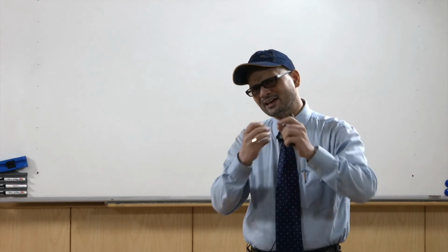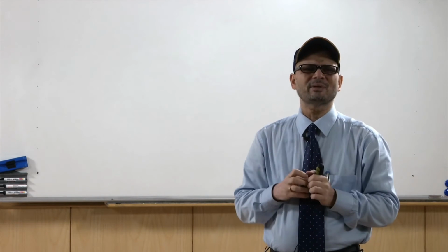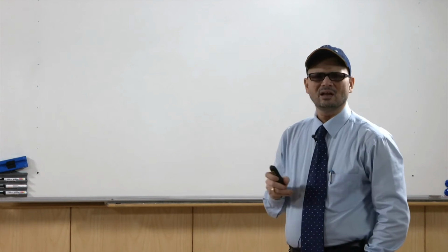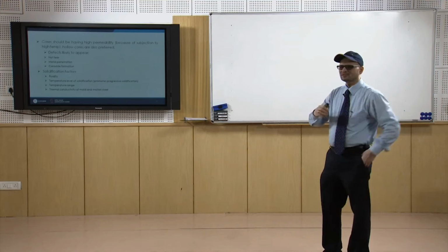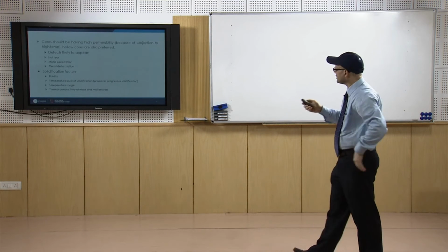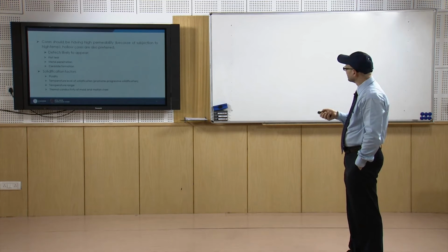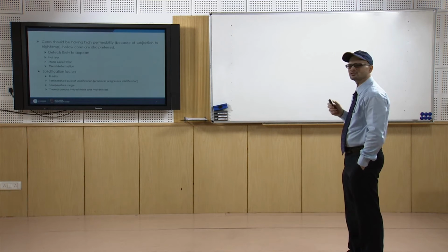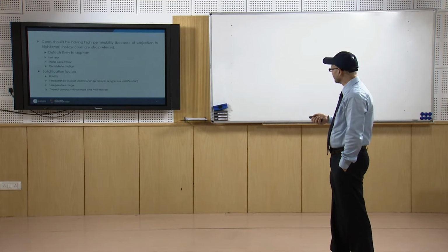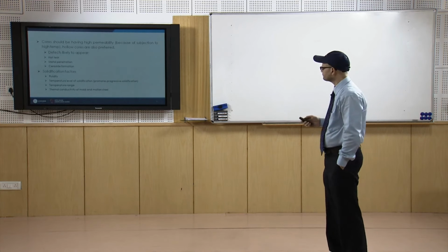So there may be tear experienced by the metal and there may be cracks formed. That is known as hot tear, and because of the large freezing range of such materials, the probability of hot tear is high in the case of steel castings. So you will have to be careful about how to minimize this hot tear.